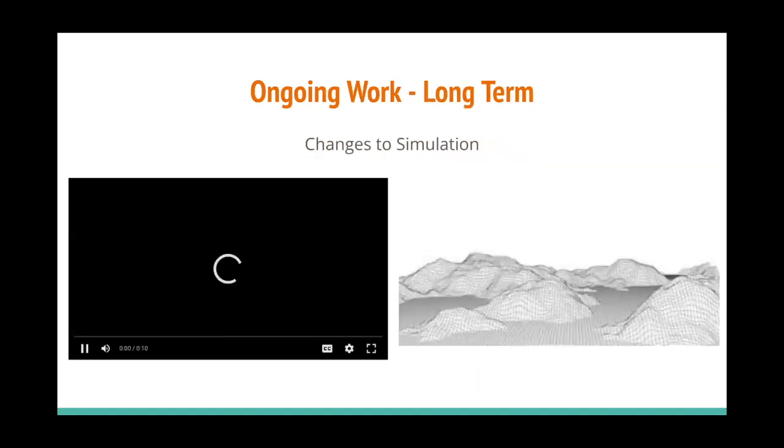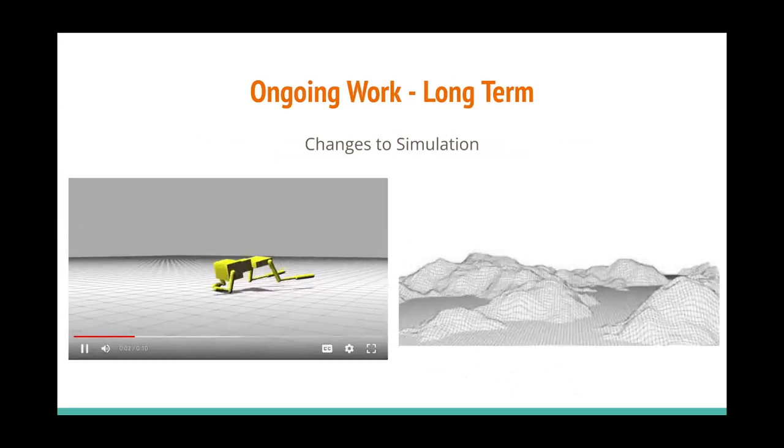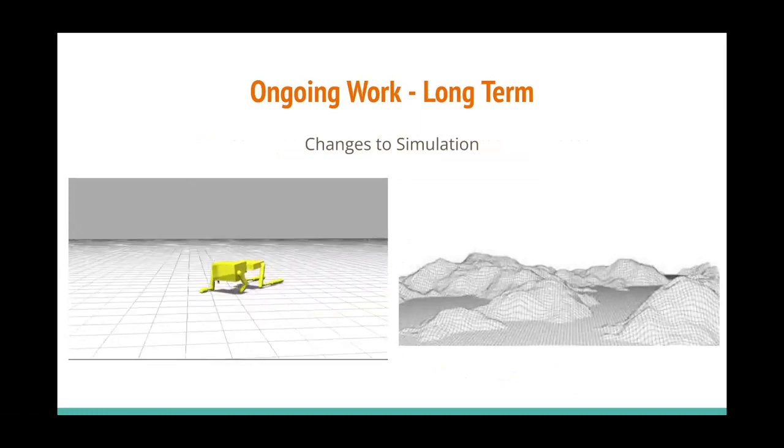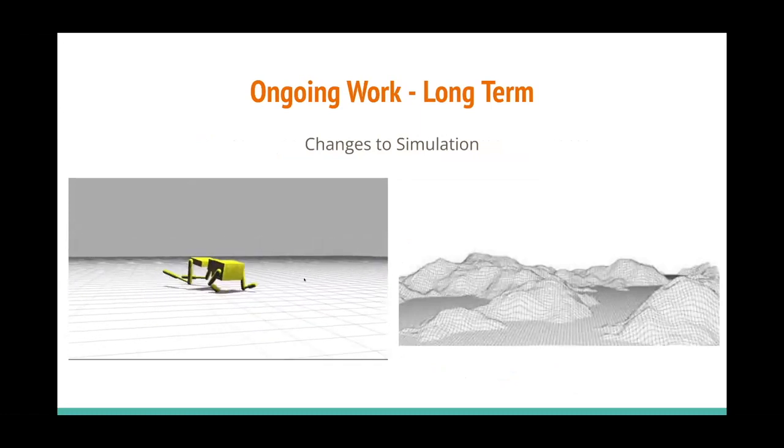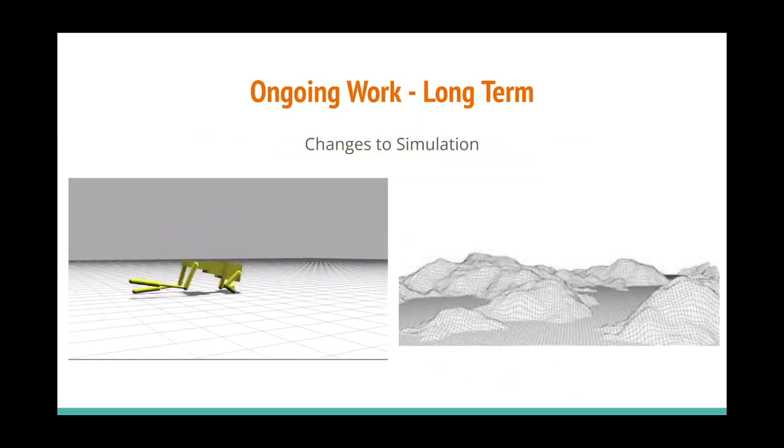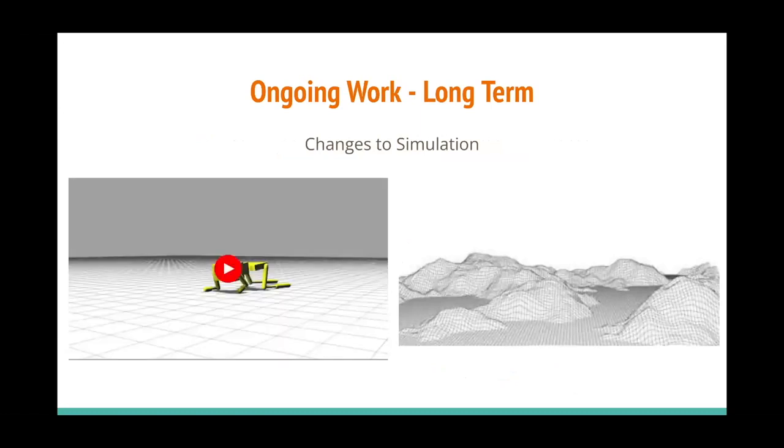And in the very long term, we'd like to make some changes to our simulation. So I'll show you this video on the left here, which is one of our walking gaits that we've developed, a very weird one, but it provides a good opportunity to look at the simulation environment. It's just flat all the way around. We're expecting our animats to sort of develop these very realistic gaits to work in the real world, but they're responding to an entirely different environment than the one that we want them to. So by adding things like terrain and obstacles and maybe differing gravities, we're hoping to create a more realistic environment. And that should help our kinematic gaits succeed where these sort of gaming gaits are currently winning.